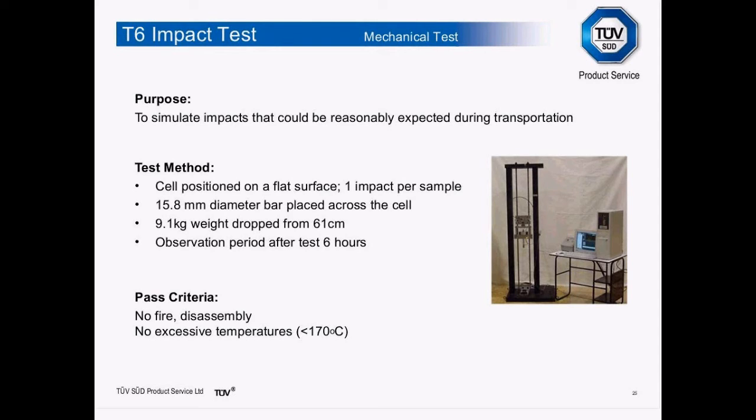Basically, 6 hours after the test, you check that there is no fire and no disassembly. During the course of the test, obviously there should be no fire or disassembly, and also during the entire test process, the cell enclosure must not exceed 170 degrees.